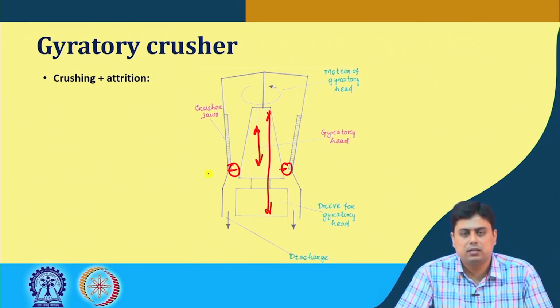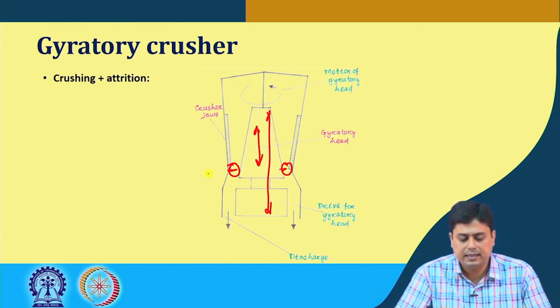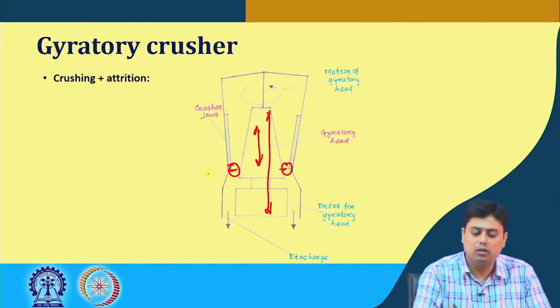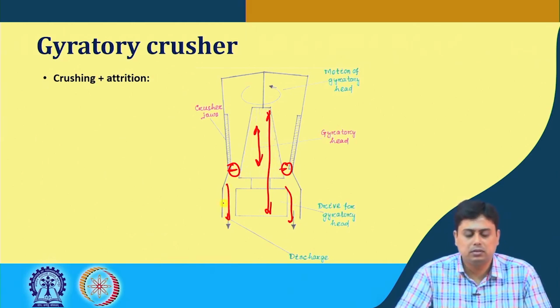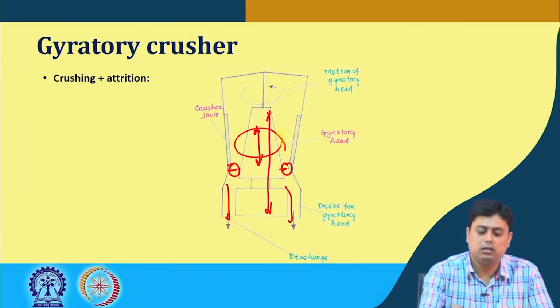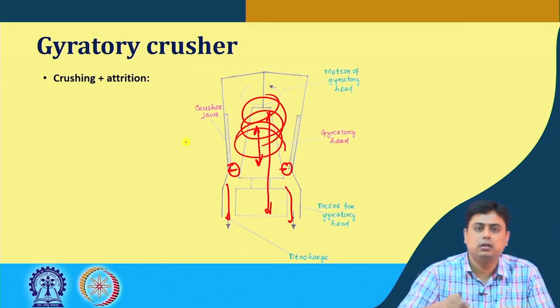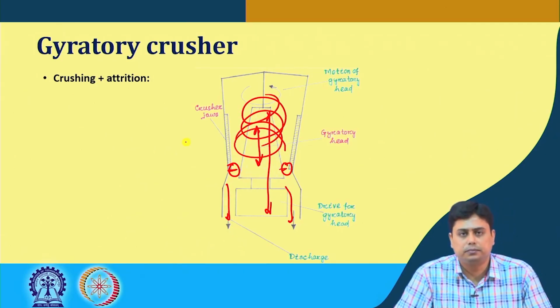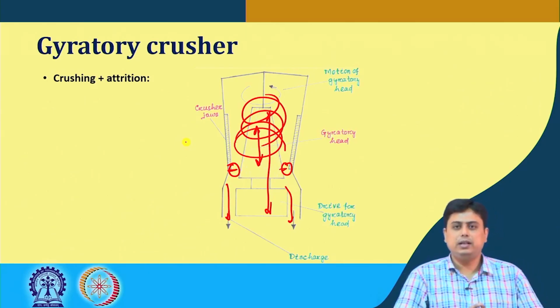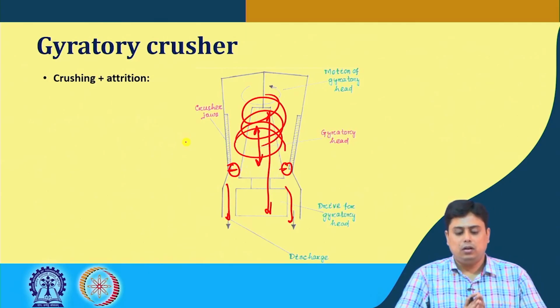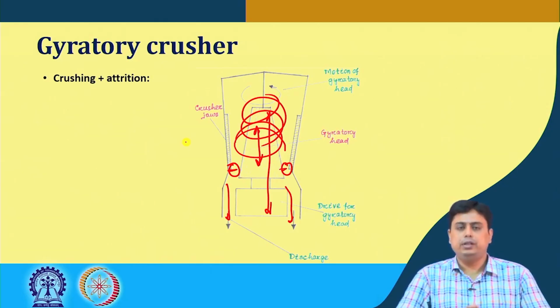So the particles of sizes lesser than this gap will come out from this chamber. Until that happens, it stays in the chamber and the crushing goes on. So one thing is very clear, that this size reduction process of handling solids is very prone to wear and tear.